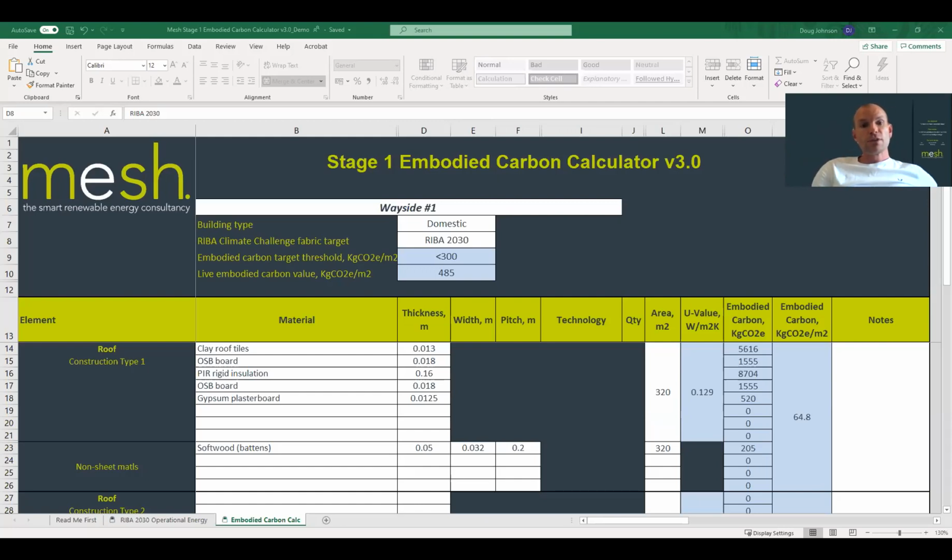What about large areas of glazed doors? I guess you put them in as windows. Jana, yeah, that's absolutely correct. So glazed doors and windows are always a bit of a tricky one. What we've assumed here is doors. When you put doors in, they are solid doors, generally speaking. If you have big glazed areas, put them in as windows. You've got big sliding doors, or maybe a proportion of your window is more glass than solid material. Put it in as windows. That's probably the best thing to do to get you the most accurate answer.